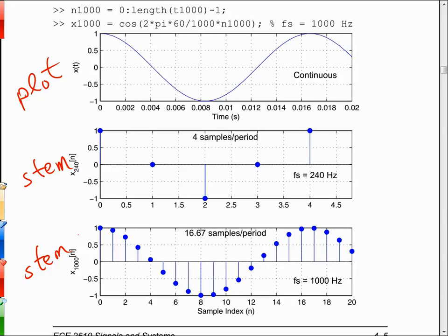The little tiny DSP board I passed around clocks at 100 megahertz, and the bigger one, that one is quite a few years old, but we still use it here. It clocks at 225 megahertz. But the processors on there, on the big board, just as an example, have quite a bit of parallelism. It's a floating point processor on the bigger board, and it can do 2 floating point multiplies and 2 floating point adds per clock cycle. So it has quite a bit of throughput capability with that architecture.